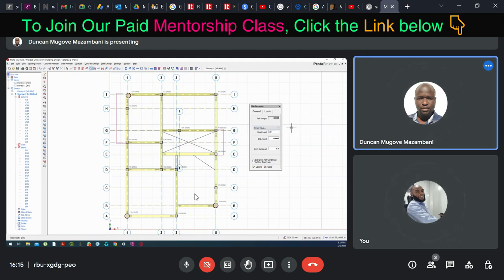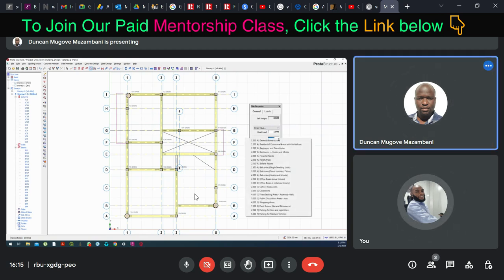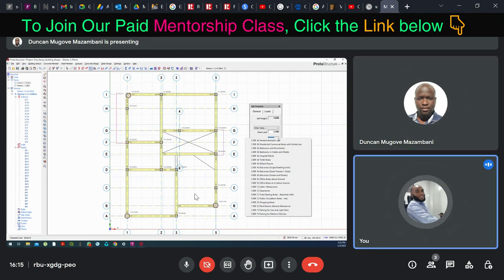Then for the imposed load, right click on that place and you will see several types of building. If you're designing a normal building, like a residential building, you use the first one, general domestic use.